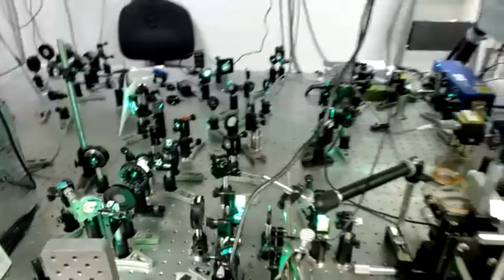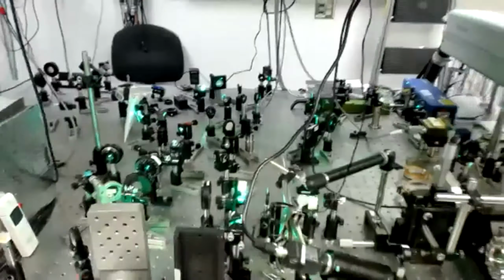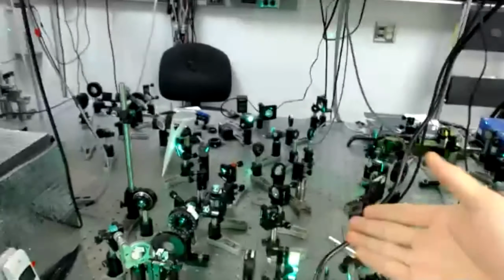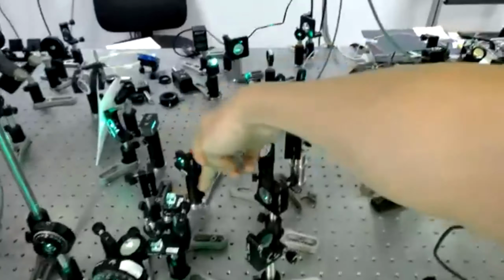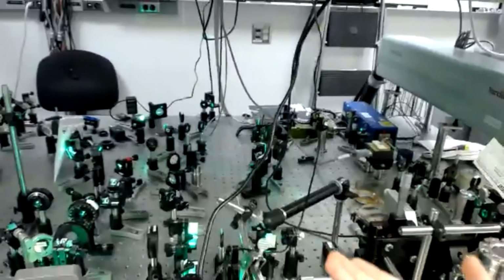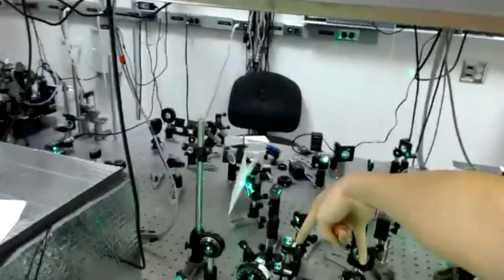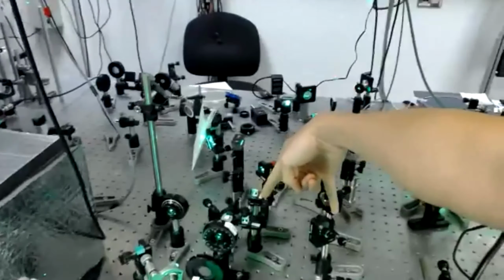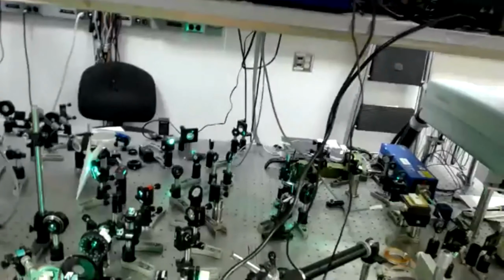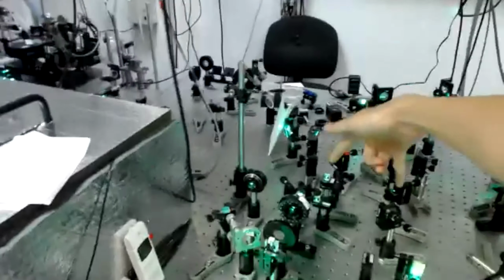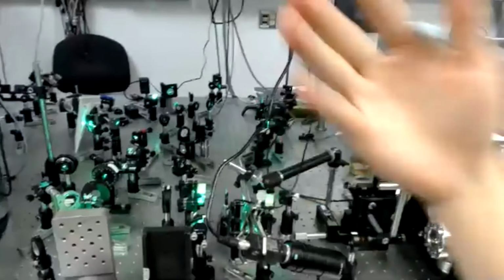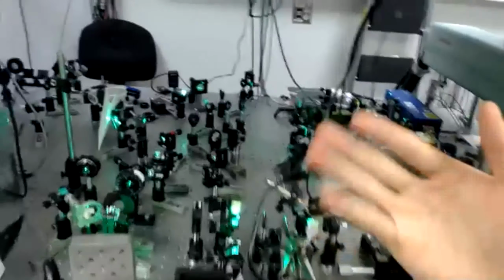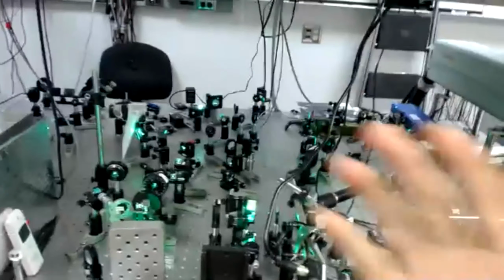But the design part takes longer because usually we have a plan, then we need to do calculations. For example, here you see this part, that's a delay arm. To make the physical length right, we have to calculate, like this maybe is 10 centimeters, we want 40 microsecond separation, then how long should this be? You may ask if it's only several centimeters or even 1 meter, the speed of light is 3 times 10 to the 8 meters per second. That's only nanosecond separation. You are very right, because this technique can down convert the time, converting nanosecond to microsecond due to the sampling of this technique.